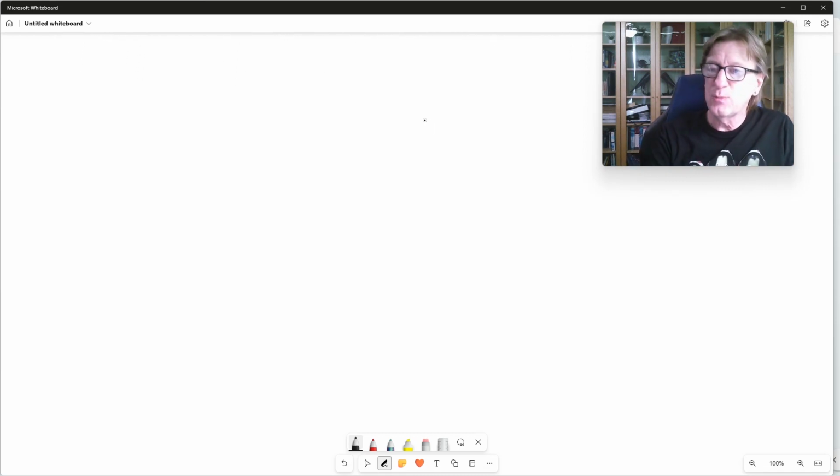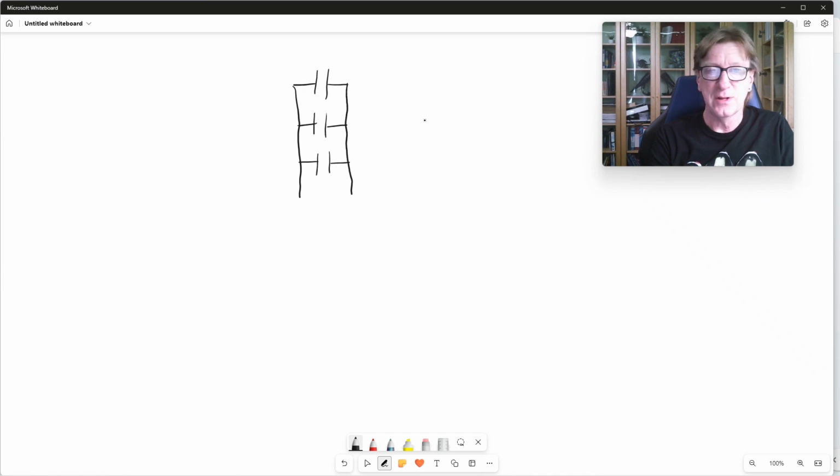If they're not in series, then we can say that maybe they're in parallel. That's the circuit that we have drawn here. They're in parallel, like this. Hopefully you can see why we call that parallel, because they're parallel to each other. The other thing to think about: they're in series if all the current that goes into one goes into the other. But if you look here, the current that comes in through here has to split, and then it splits again. And so the current through each one of these capacitors cannot be the same as the original current.